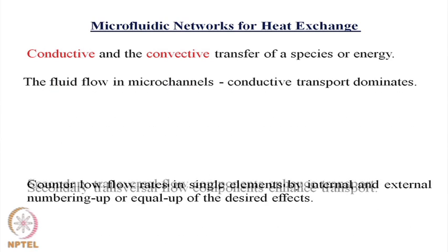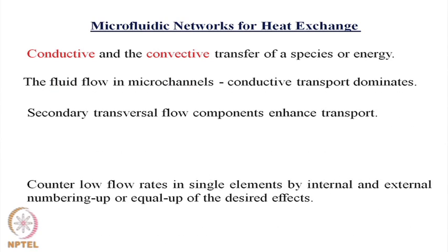flow velocity. Now, we come to an interesting part, which is what I wanted to discuss in this class: microfluidic networks for heat exchange. Conductive and convective transfer of a species or energy is the focus of creating microfluidic networks. So, it can be used for heat exchange, and it can very well be used for mass transfer as well.